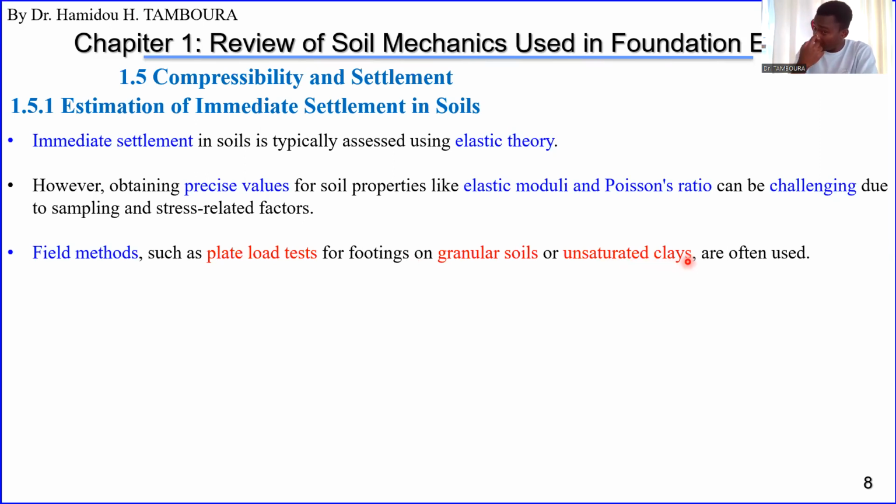Within these two, please notice that there is no saturated clay for the plate loading test. Granular soil, for example, sand or gravel, is okay. Unsaturated clay, maybe okay. If you are dealing with saturated clay, it's not included in this first part. The second part of this video will be about saturated clay.